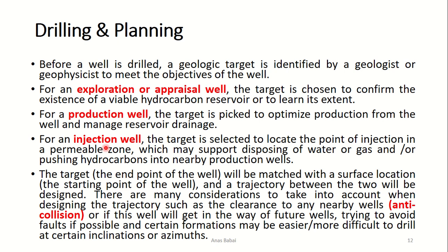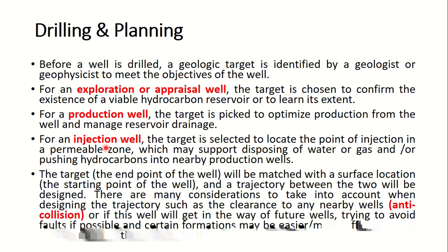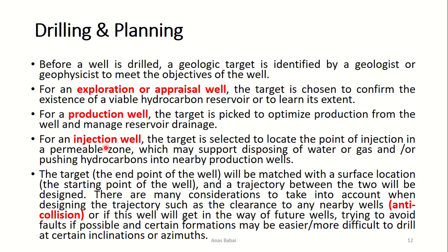This can be done by injection wells, in which we inject fluid or gas in one well and produce in another well, in order to push the hydrocarbon located in the reservoir to be extracted or to be directed to a specific well for production. Not to forget to mention that recently there is another technique for this enhanced oil recovery.